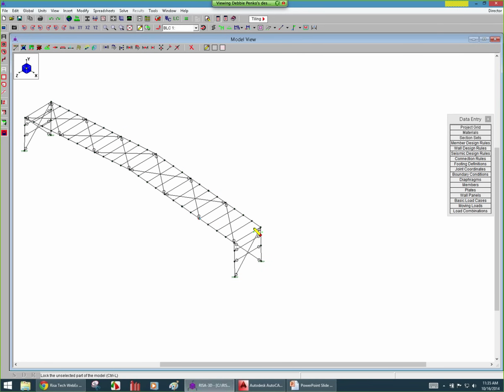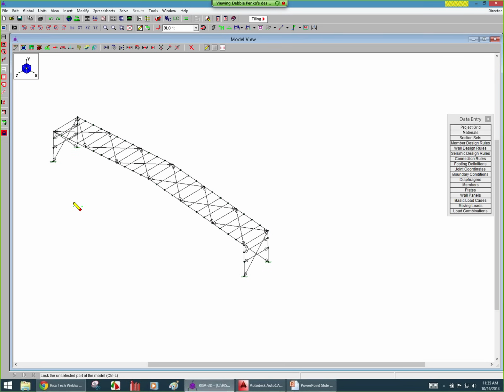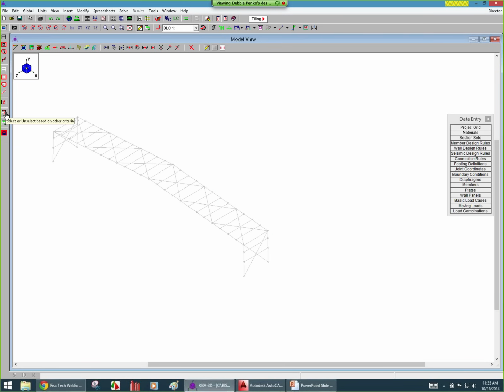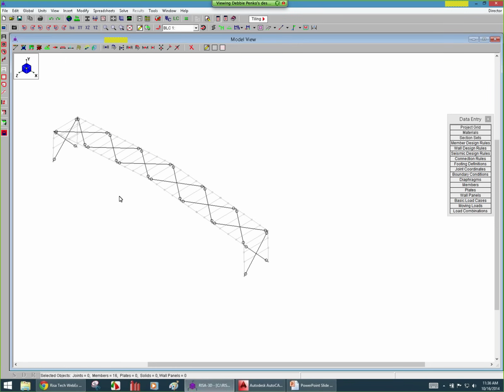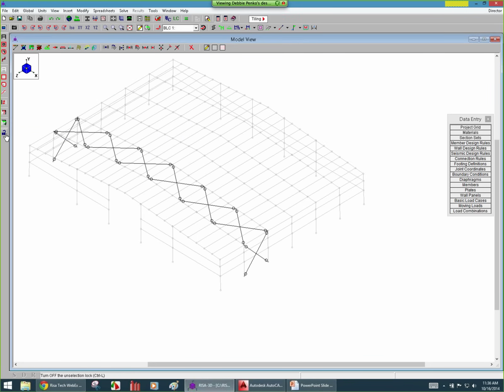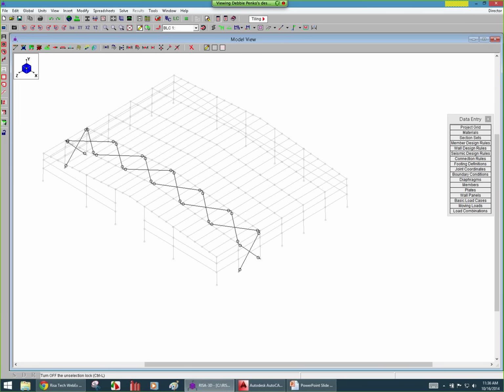When you finish that, again, unselect everything and just pick up those cable elements. Finding on this list just the 3/8 inch cable, select only those. I do like to unlock everything. You don't need to unlock everything, but it helps me guide myself and make sure that I got this correctly when I do the copy.